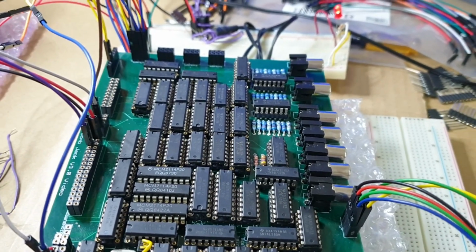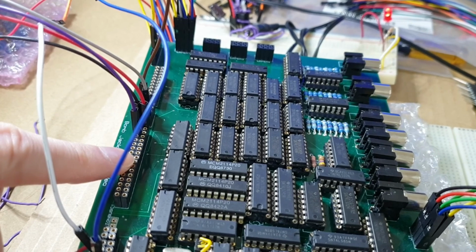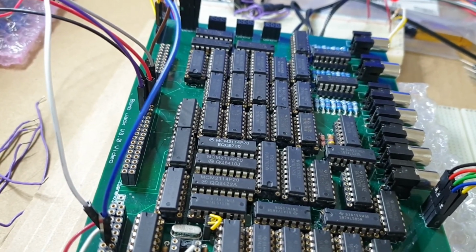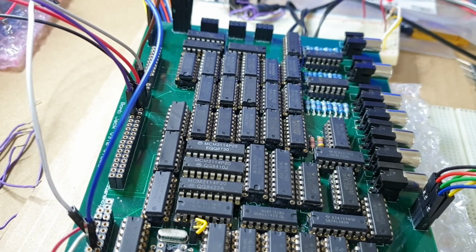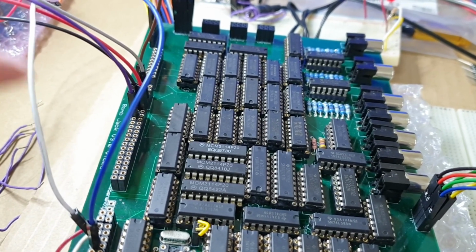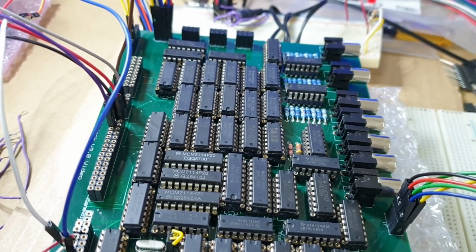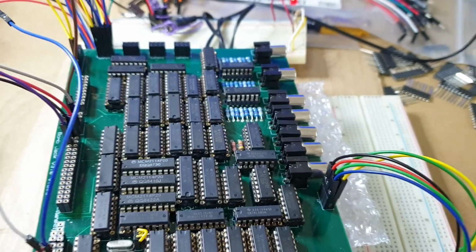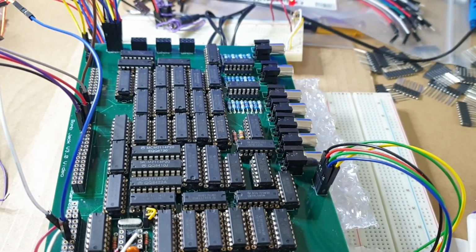Because for ease of debugging, it's great to be able to whack these wires into the top of these headers here, and debugging is important. However, for interconnect stability, it's going to be better to have, I think, the right-angled IDC connectors. Maybe a hybrid combination for the next generation of the board.